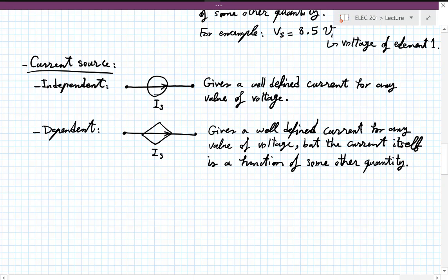An example of a current source from this abstract point of view is something that, when you put it in the circuit, forces, let's say, 3 amps going that way at the circuit level element. If you're wondering how you would make one in practice, very simple examples would be with a transistor. You can think of a simple circuit called a current mirror with 2 transistors.